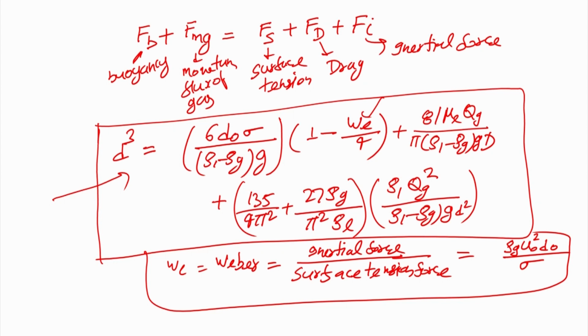We are not discussing the bubble size distribution again. We are just saying that if you inject gas in the column, you can calculate what the bubble size will be, and you can use this bubble size in your simulation to calculate the drag. Other parameters about the bubble shape and bubble velocity we will discuss in the next class. Thank you.